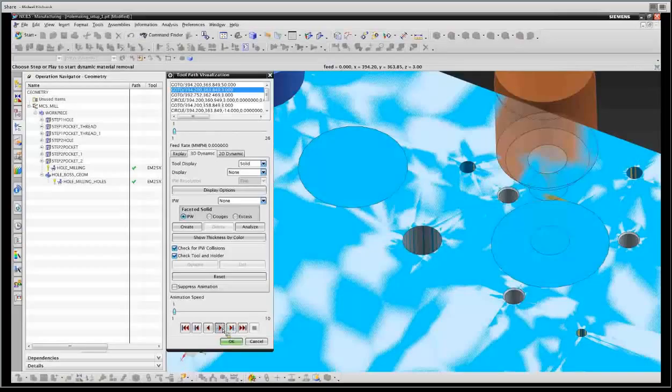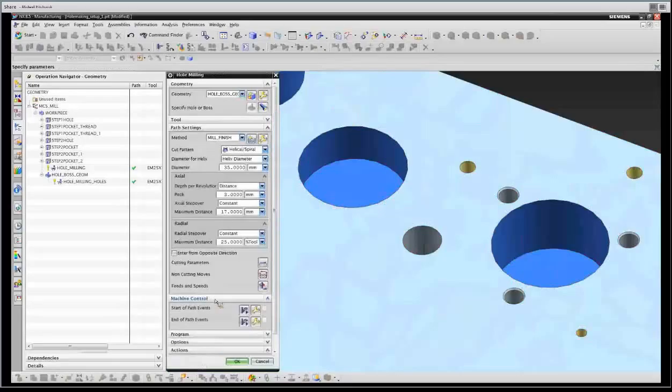And I think this is a pretty efficient way. And again, this is all arcs. You get a helix going down the middle that's a true helix, and each of those moves out. There's always an option for you to go to machine control or in your posts linearize it. Actually, we don't put that option in here because we figure if you're cutting it this way, you want arcs and not points. You can customize in a linear ability for some reason, if you really want lots of data, because if you have a 5 meg file going out, it looks like you're doing more work than if you just have one that's a couple meg or something.